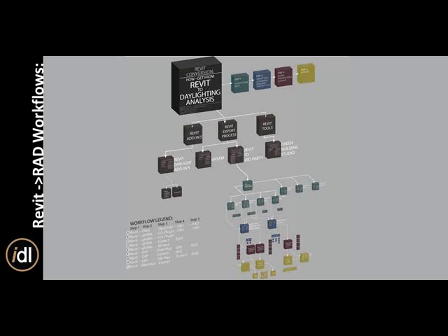Sure. So the question is, what exactly are daylight analysis outputs in general? There are a couple of different categories. One would be illuminance maps, so we could put a grid of analysis points in a room like this and run it during either annual time steps or a single point in time, and it would give you the amount of foot-candles or lux falling into the space. That's what LEED looks for as its metrics.